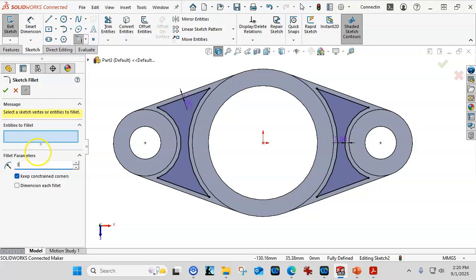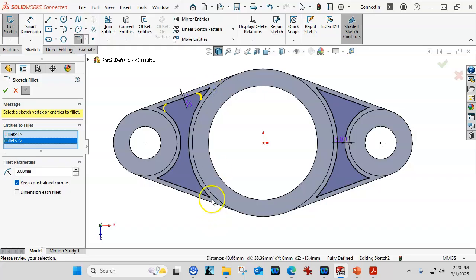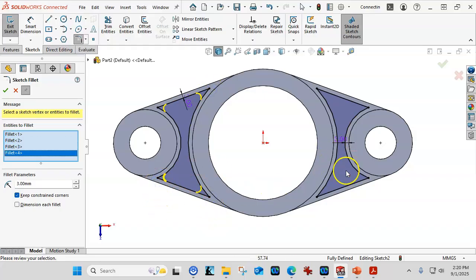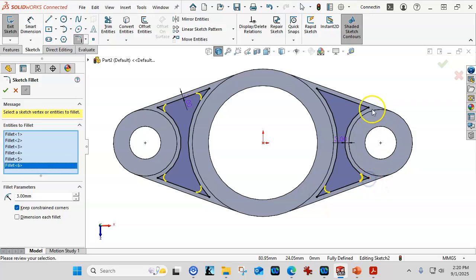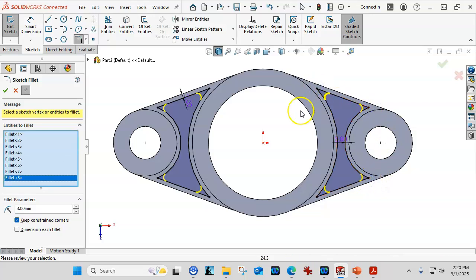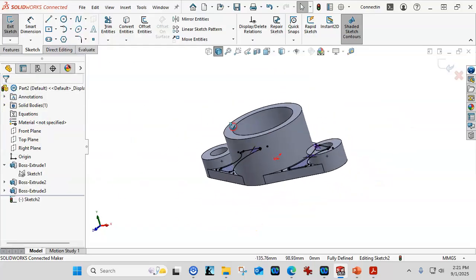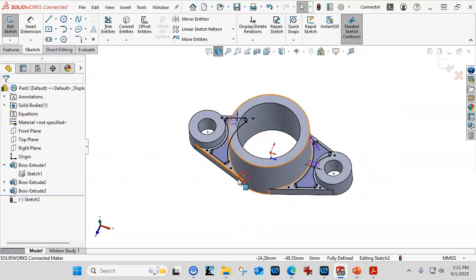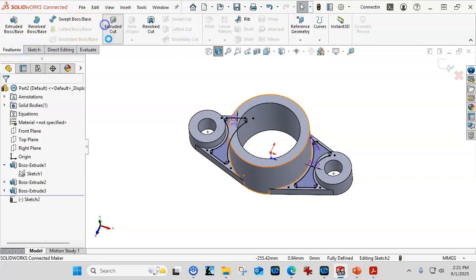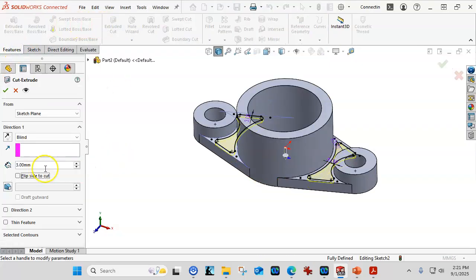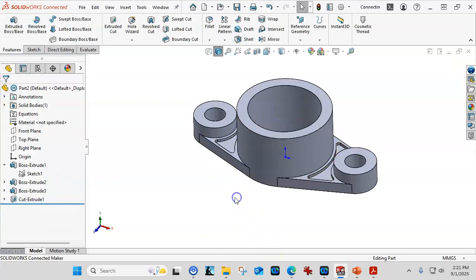So let's go to 3 millimeters so it has a chance to actually solve, and we'll put those in place and just keep clicking on those vertices until we get it there. And we go ahead and hit OK. Oh, sorry, not a depth, the fillet is actually 3 millimeters. Now we can do the extruded cut and go 3 millimeters there, and go ahead and hit OK.